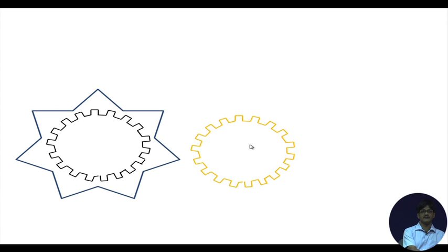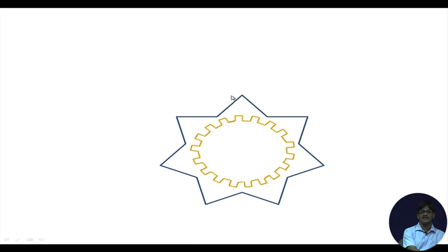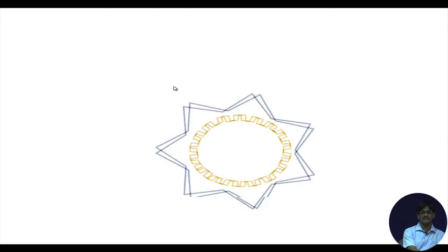Splined shaft is rotating, and this is a hypothetical, virtual member, a machine element with a hollow interior with fitting splined teeth. These teeth match exactly with these external teeth. So, these are internally cut teeth in this hollow member, these are external teeth, so that if they are assembled, they will have the same rotations per minute this way.